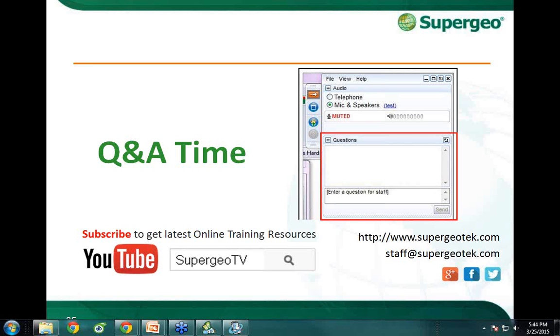We also have a question about users who don't have a reference station or a public NTRIP service. If you have this problem, you can use post-processing and select the station that is nearest to you. Maybe not all the stations will be in your country, but you can use a station near your country. This will be okay.